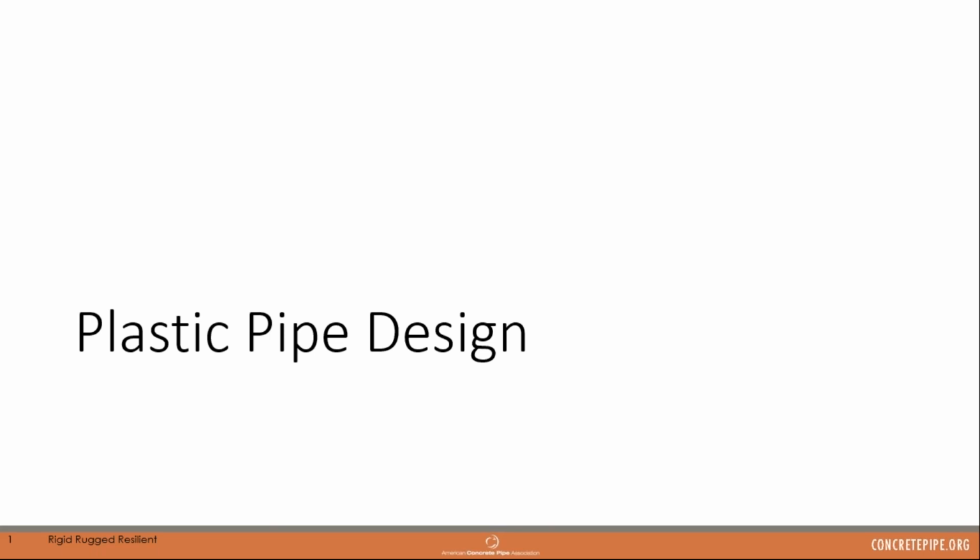So in those more specialized cases, that would be when you want to look at using PipePack possibly. And then if you go beyond those fill height tables of a class 5, if you need something more than a class 5, our manufacturers can actually do what Paul mentioned as a direct design and build a special product for you that will still meet the needs of those specialty loading situations.